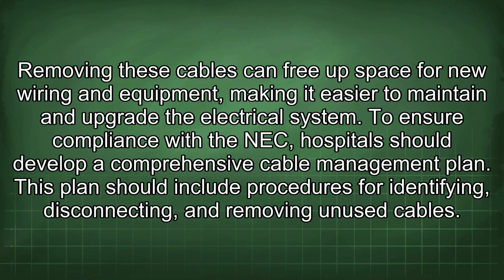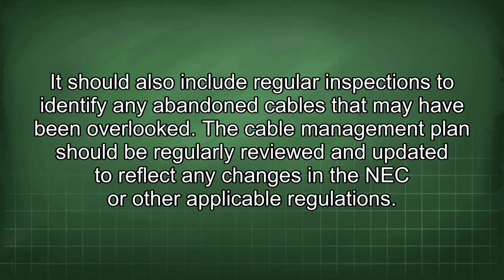Removing these cables can free up space for new wiring and equipment, making it easier to maintain and upgrade the electrical system. To ensure compliance with the NEC, hospitals should develop a comprehensive cable management plan. This plan should include procedures for identifying, disconnecting, and removing unused cables. It should also include regular inspections to identify any abandoned cables that may have been overlooked. The cable management plan should be regularly reviewed and updated to reflect any changes in the NEC or other applicable